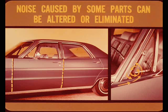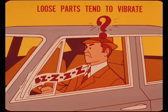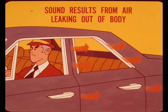Turbulence noise caused by some protruding parts is a different story because it can often be altered or eliminated. Common examples of this condition are doors with front edges set out from the body surface and moldings which extend into the air stream. Loose parts not only set up turbulence but also tend to vibrate or buzz. This kind of noise can be quite disturbing, but in most cases it's fairly easy to track down and correct. Another basic source of noise is body air leaks.